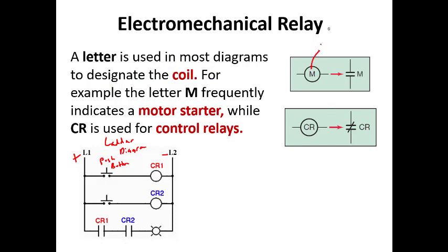M means that it would start a motor. So what we're looking at is how are these contacts connected? Are they connected to a motor? So that would look like this. So maybe we have a motor here, and our contacts are connected to a motor, so we decided to call this M or M1 or MS1. So this would be motor starter is what MS stands for. And all of the coils usually will have their own unique name. They'll be labeled in the panel with the name.